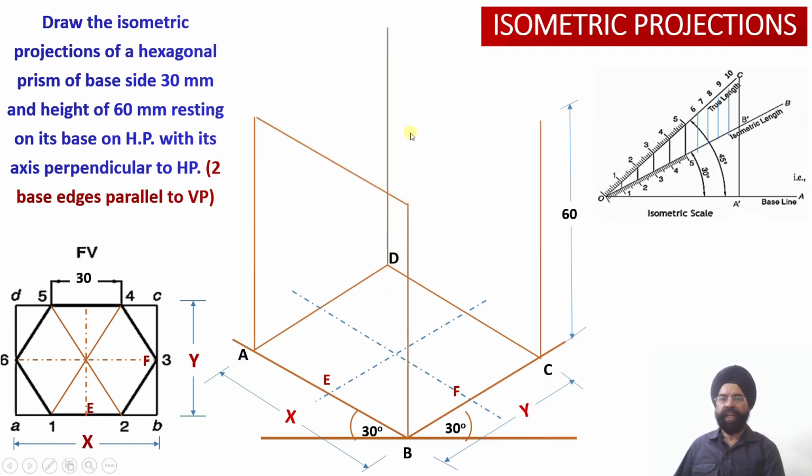So just check 1, 2 and 3. So these isometric lines have been drawn and are equal to this y axis. Now I am going to complete the top face. So again 4 isometric lines I will be requiring, 1, 2, 3 and 4. So this way the top face of this particular hexagonal prism has been developed. Now I am getting a rectangular prism in this case, which is going to form a guideline for developing this hexagonal prism construction as it is standing upright over there.